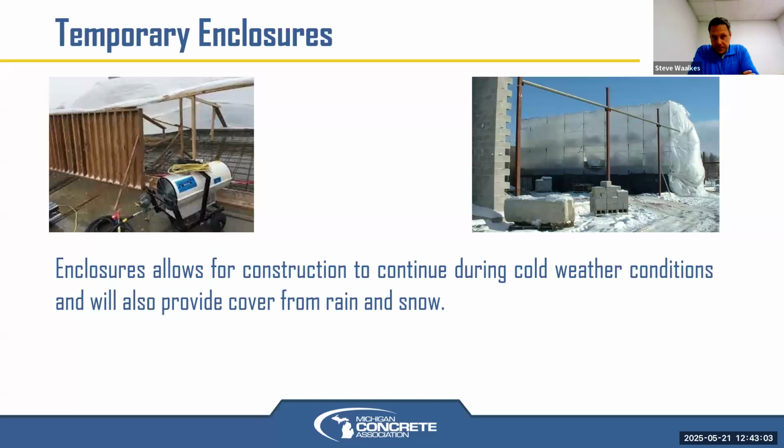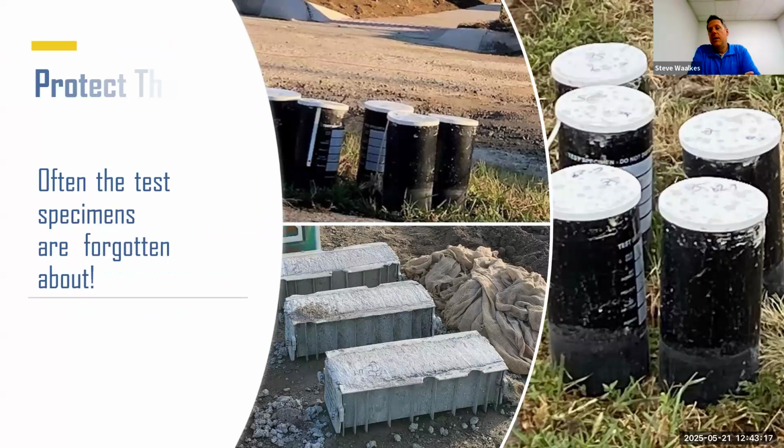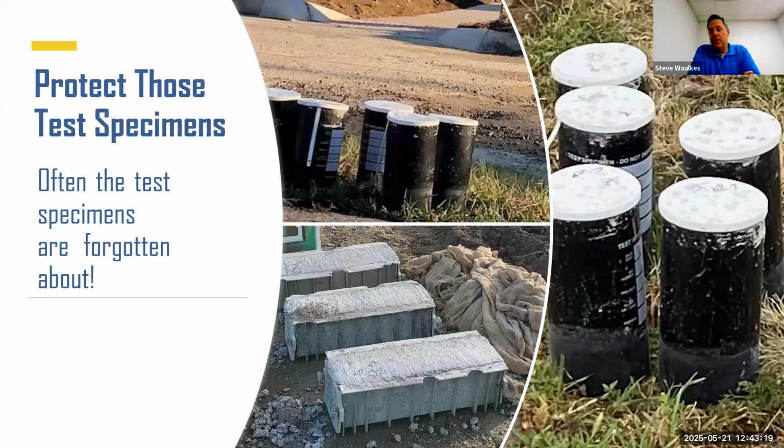In wintertime, it may mean that you have to provide artificial heat. There are coolers for these cylinders or beams that you can put them in that actually provide artificial heat, or you should put them in the same area as long as it's 60 to 80 degrees, because that is the requirement, that they be maintained in the field between 60 and 80. So you need to have assurance that that is what is occurring.